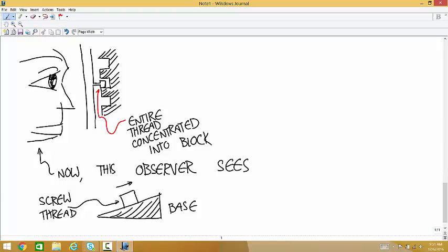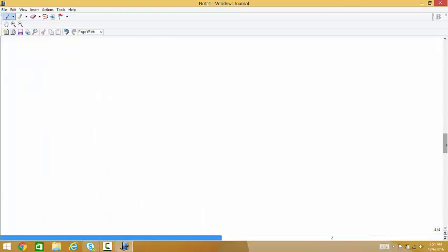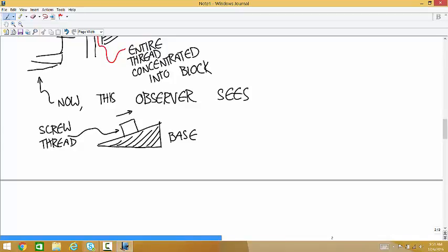So now all we need to do is figure out what to do the math. We need the angle of the incline. We need the magnitude of the downward force W in the picture that I drew earlier, and we need the horizontal force Q. And that's all we need to come up with. And then we're going to treat this problem as if the screw sliding up this ramp is just this block sliding up a ramp.